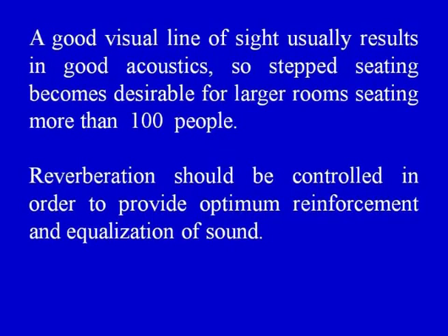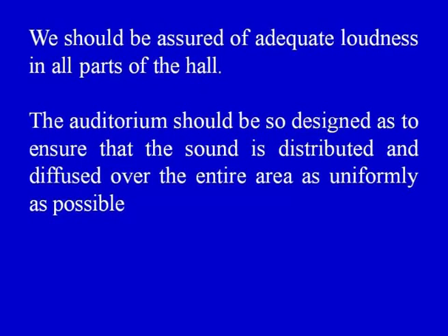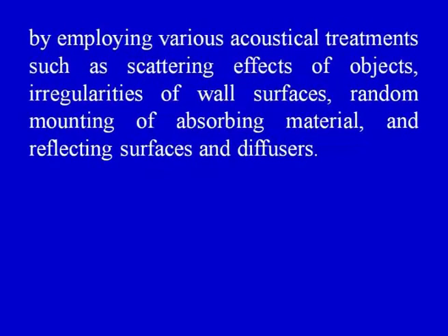Reverberation should be controlled in order to provide optimum reinforcement and equalization of sound. We should be assured of adequate loudness in all parts of the hall. The auditorium should be so designed as to ensure that the sound is distributed and diffused over the entire area as uniformly as possible by employing various acoustical treatments such as scattering effects of objects, irregularities of wall surfaces, random mounting of absorbing material, and reflecting